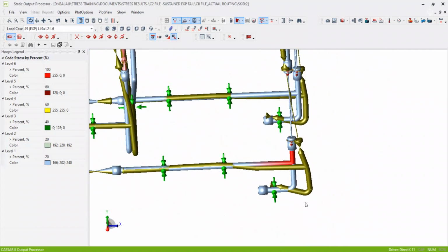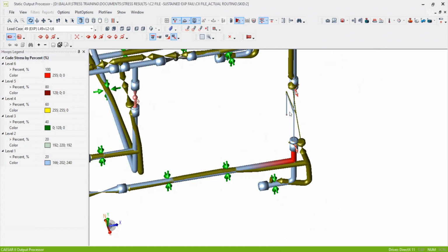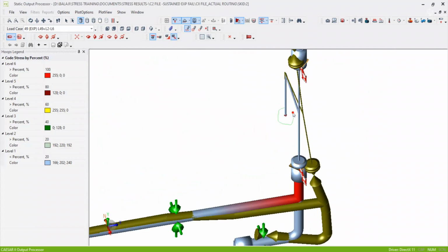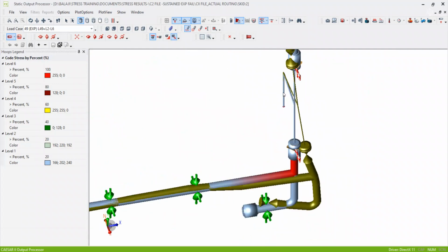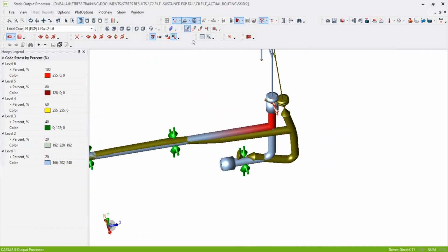At this point, you see, our anchor is here. This equipment is one of the pumps. So this is the anchor; here they have provided the anchor. What happens is your pipe is moving like this and going down. So your movement is in the downward direction. What they have done is added a support at this location, which means they are arresting this movement.